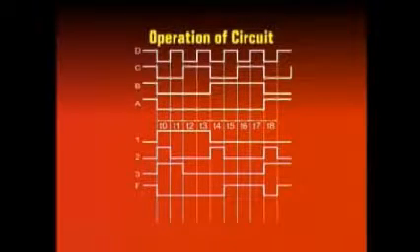The timing signal F represents the active low output. At interval T0, the active low input at inputs A, B, C, D is 0, 0, 0, 0, which actually represents 1, 1, 1, 1. The active low output F is 0, which indicates that adjacent ones have been detected.